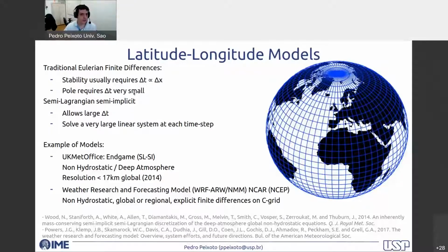One of the solutions for this is to change your numerics formulation into something that allows larger time steps and avoids CFL. The way of doing that is if you use semi-Lagrangian. What does that mean? In the advection terms, you follow your Lagrangian path, you follow the particles, you follow Lagrangian trajectories, but it's only semi.